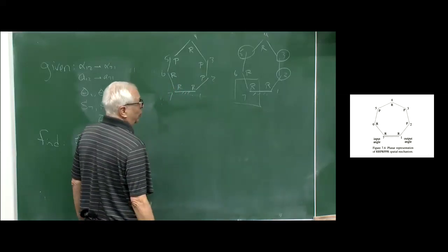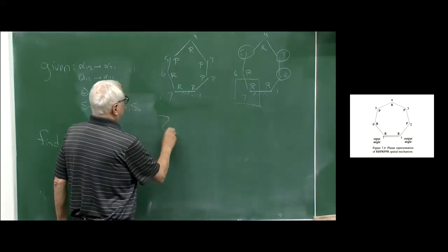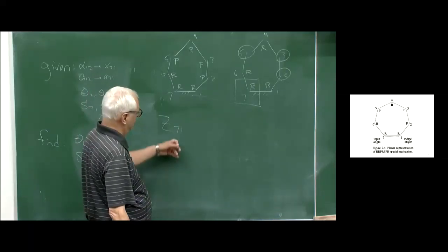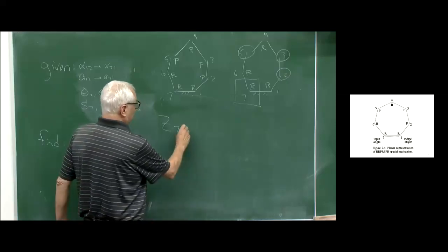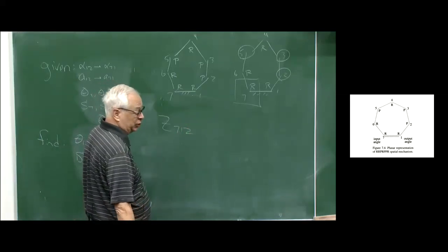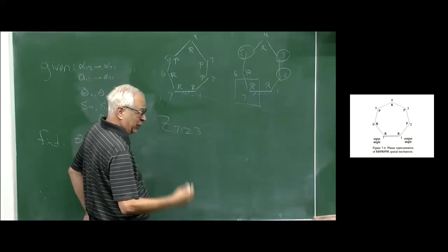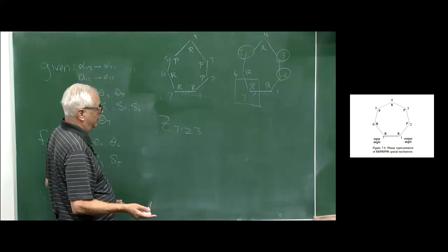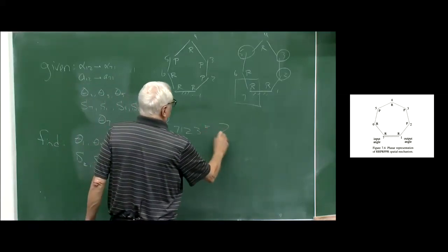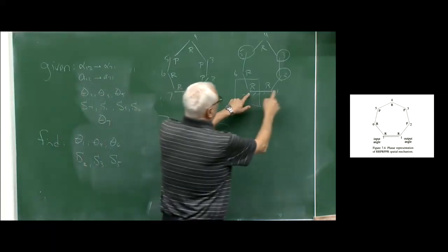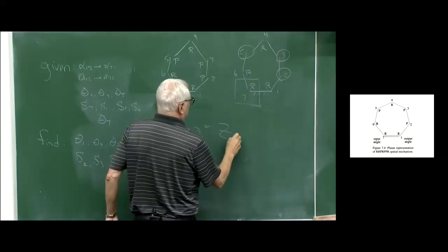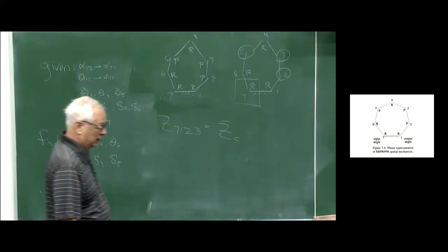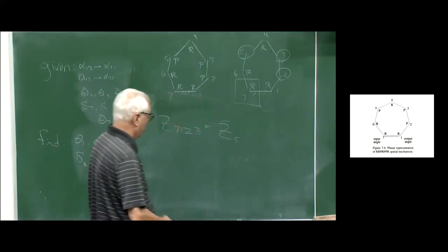I'm going to go for theta 1 first. So I'm going to say, well, Z7, yeah. 1, yeah, I want 1. Right, 7 was given. I want 1 because that's what I'm looking for. It's okay to put 2 because prismatic joint there. It's okay to put 3. If I could get 1 more into C, I'd have a fundamental law, but I don't want to put 4. So I'm going to stop. Turns out then it's a subsidiary, and 7, 1, 2, 3, Z5 or Z5 bar. Wow. So we went into the toolbox and found, just like we did in chapter 6, 1 equation and 1 unknown.